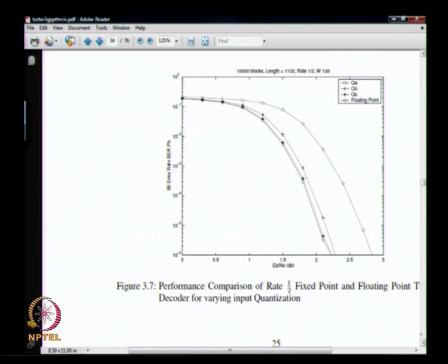What is this? This is for rate half. Again, for rate half, the 3GPP will specify how to go from rate 1/3 to rate half. I believe it's even and odd puncturing. When you do that, you go to rate half, and you see it's not as good as rate 1/3, right? The coding gain is dropped. But then you gain in rate. Still there is significant coding gain. You get 10⁻⁶ bit error rate at around 2.2, 2.3 Eb/N0. That is still about 8 dB of coding gain at rate half, which is really good.